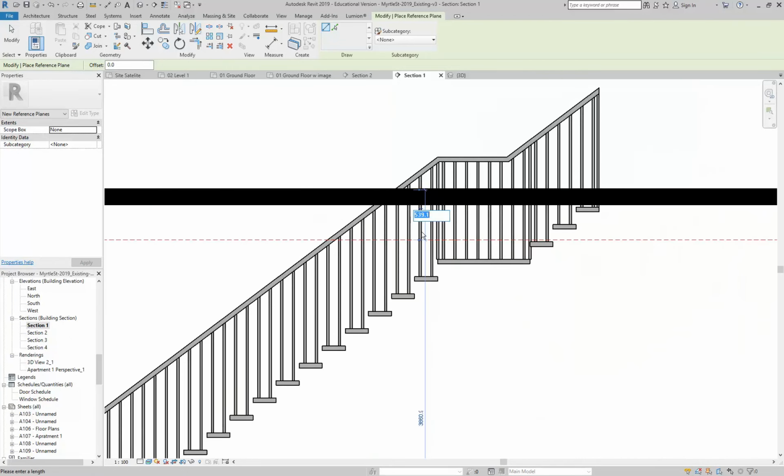And then we'd say the minimum distance between your floor and the bottom of your ceiling. If you really push it, this is probably pushing it a bit too much, but we'll say you can go to 250 because I know you pushed for space. Yeah, you can do it. If you line your joists, you can go down to that. So that would mean floor joists. You could have 200mm floor joists with 20mm of flooring above. That's the absolute minimum. That's pushing it to the limit. Yeah, that's if you get down to 200 joists, which you can easily. So you could potentially do that, but it is pushing it.